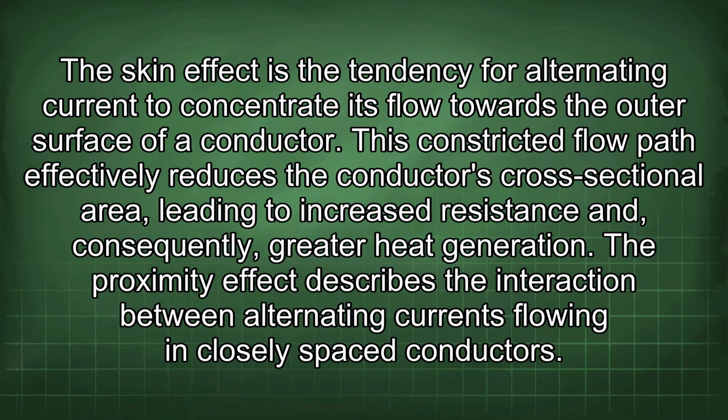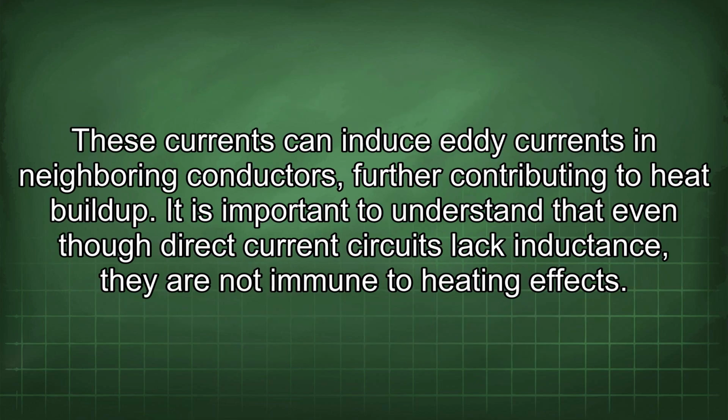The skin effect is the tendency for alternating current to concentrate its flow towards the outer surface of a conductor. This constrictive flow path effectively reduces the conductor's cross-sectional area, leading to increased resistance and, consequently, greater heat generation. The proximity effect describes the interaction between alternating currents flowing in closely spaced conductors. These currents can induce eddy currents in neighboring conductors, further contributing to heat buildup.